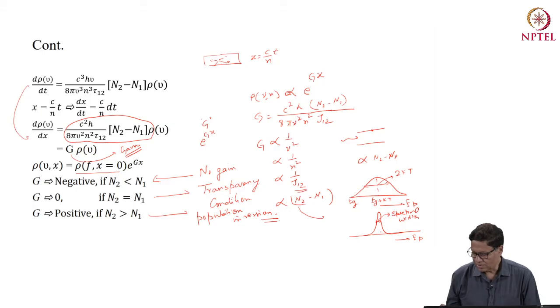The spectral width of a laser diode is very, very low, and a typical laser diode has a spectral width of 0.1 nanometer to a few nanometers. Whereas in the LED case, we had calculated the order of 70 to 100 nanometer. So we can now say that this source is temporally coherent.